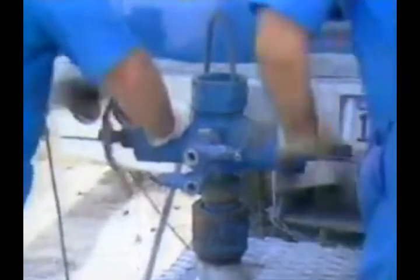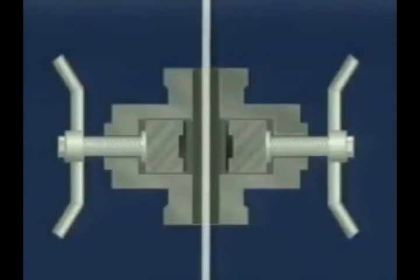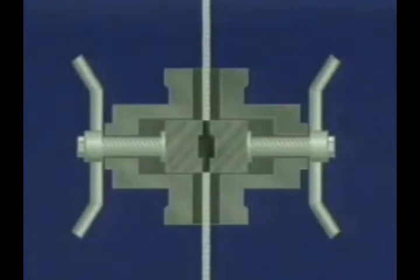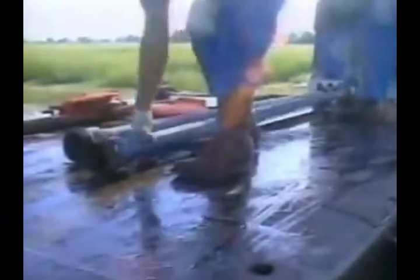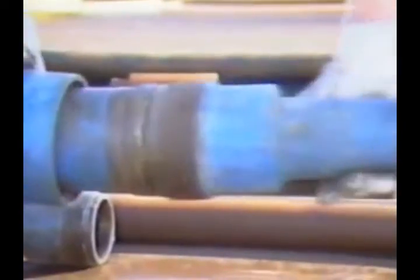The assembly consists of a blowout preventer, a riser pipe to contain the perforating tools, a flow tube assembly, and an upper seal or stuffing box. When closed, the blowout preventer seals tightly around the cable, preventing pressure from communicating around the cable with the riser. The riser pipe consists of pipe sections with quick connect couplings. These couplings are designed to let the internal riser pressure work to maintain the coupling seal.